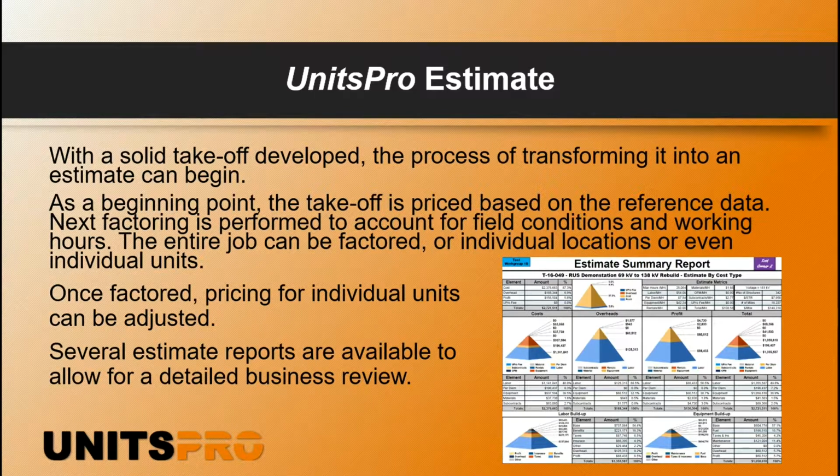They also validate that takeoff. Very important is any temporary work. You have a road crossing on a transmission line installation. You need to put up guard structures. Go ahead and make a location for that. Add those guard structures in. Make sure that the work necessary to complete this installation is included in our takeoff and therefore in our estimate.